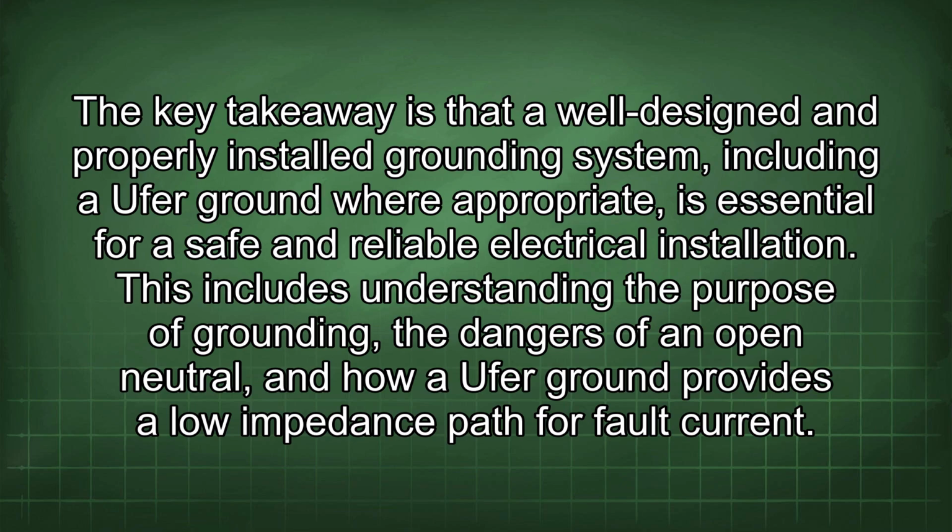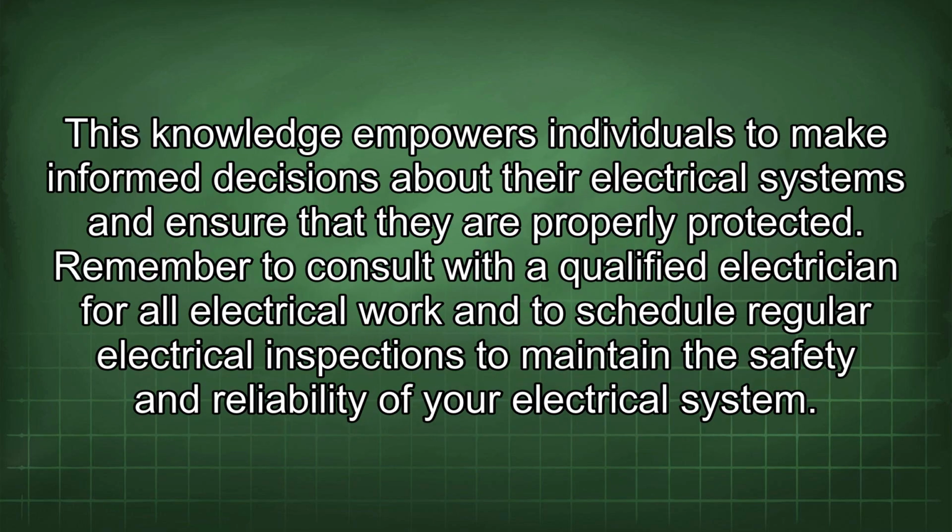This includes understanding the purpose of grounding, the dangers of an open neutral, and how a Ufer ground provides a low impedance path for fault current. This knowledge empowers individuals to make informed decisions about their electrical systems and ensure that they are properly protected. Remember to consult with a qualified electrician for all electrical work and to schedule regular electrical inspections to maintain the safety and reliability of your electrical system.